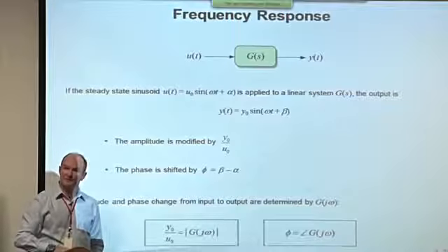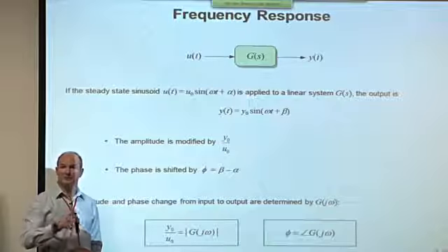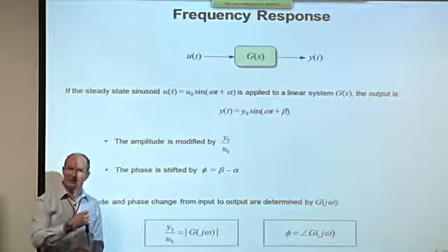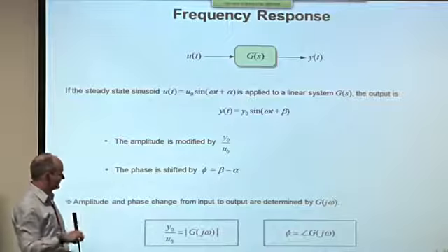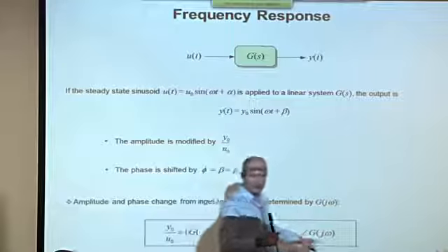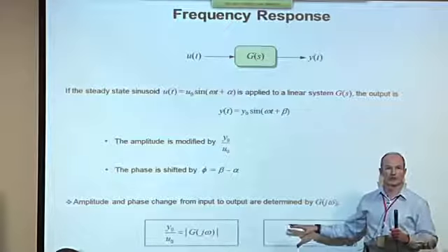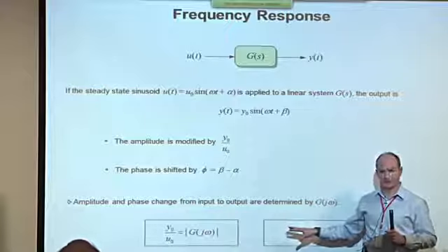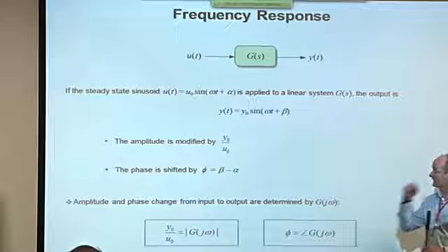We can plot these two variables in various ways, the best known being the Bode plot, where they're plotted on two separate graphs with log linear axes. These are called the modulus and the argument, of course, and these are the response of the transfer function, the numerical value of the transfer function as a function of frequency. So every transfer function has a frequency response measured in this way.